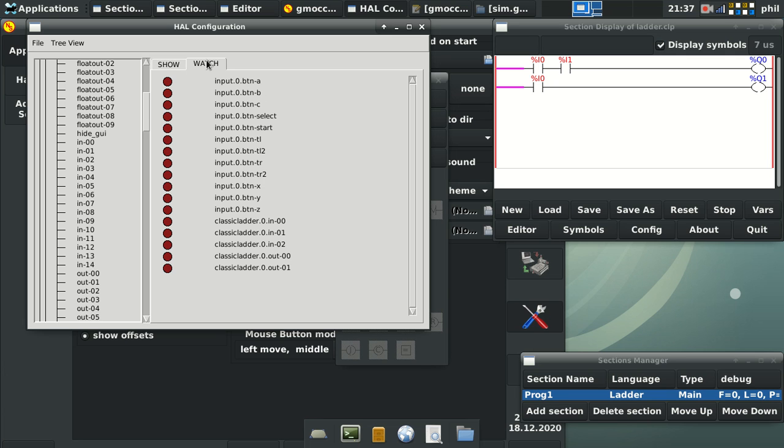Only by holding in the select key and pressing button B will the circuit become complete and send the output to LinuxCNC. The outputs can be used internally within LinuxCNC, or they can be used externally, again, to trigger relays and other things within your electrical cabinet.